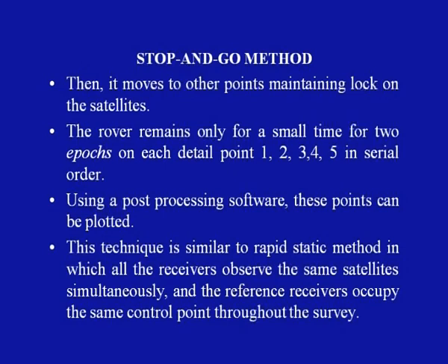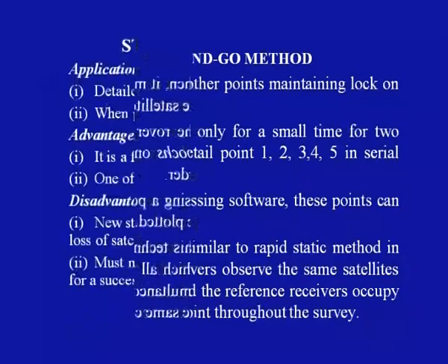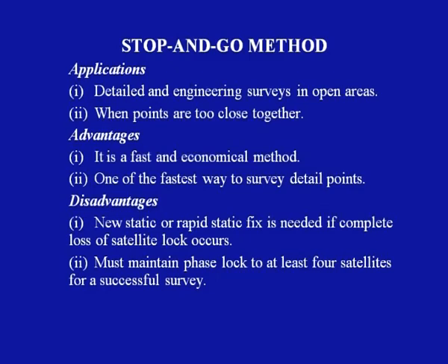This technique is similar to the rapid static method, in which all the receivers observe the same satellites simultaneously and the reference receiver occupies the same control point throughout the survey. Applications include detailed and engineering surveys in open areas, and cases when the points of observation are too close to each other.